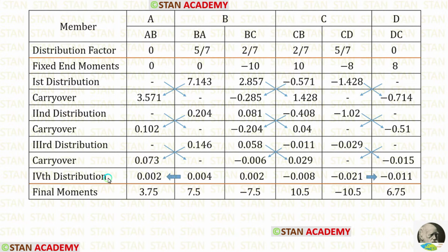I have done up to the fourth distribution. I have stopped in the fourth distribution because in the fourth distribution I am getting very small values. In the last distribution, we have to give the carryover to the fixed ends.